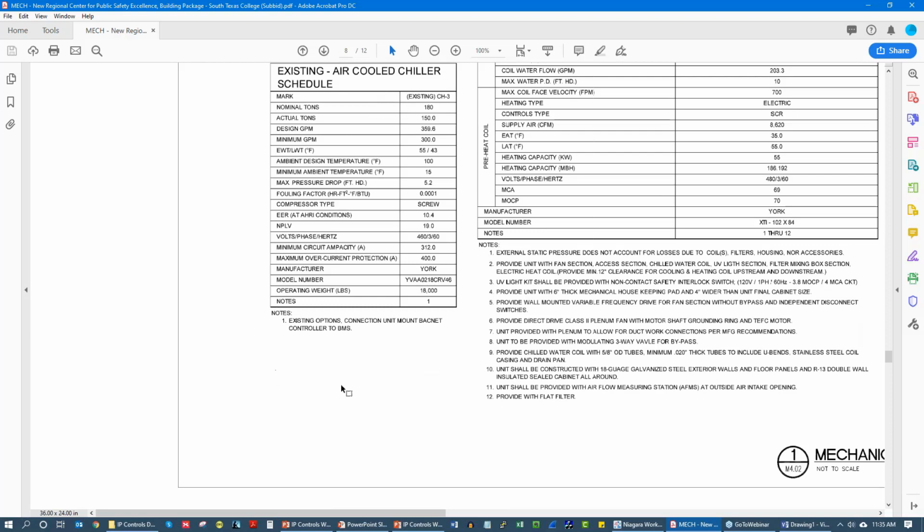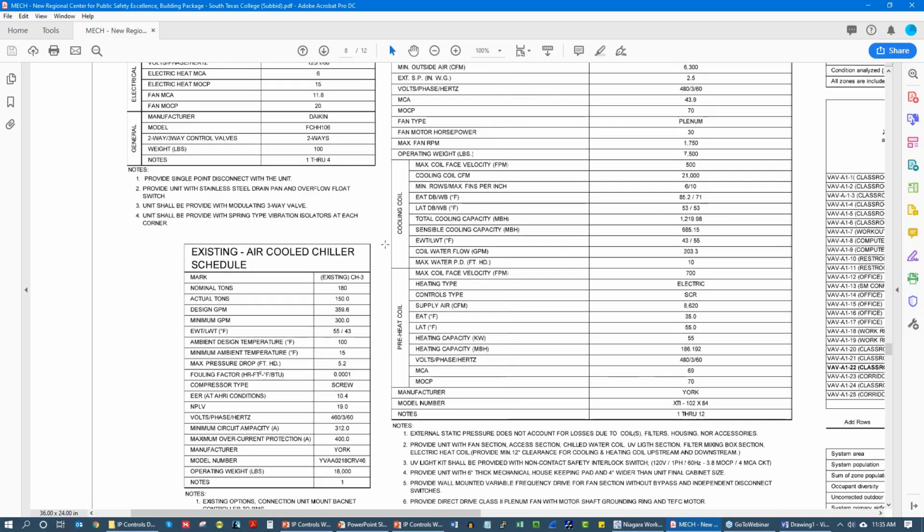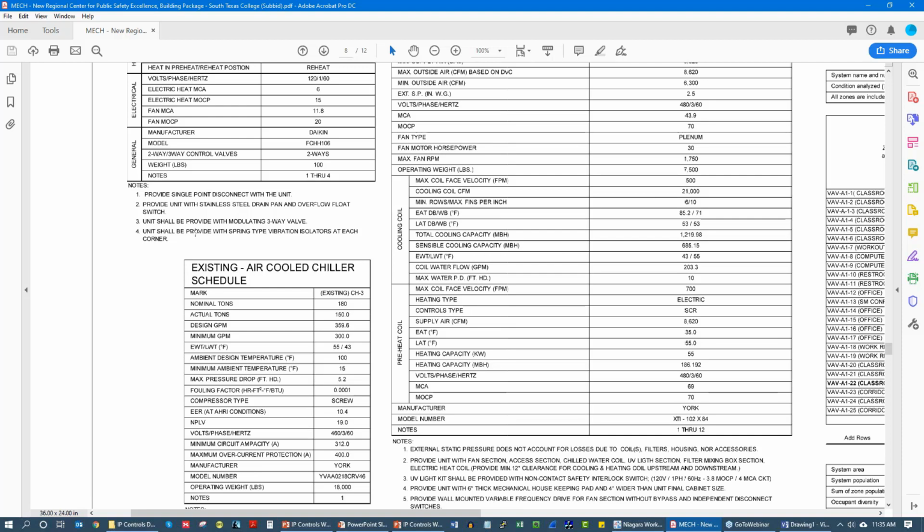So we know we have 28 devices. We know we are going to need, at a minimum, one port for the bus and 3 ports for the star, and probably a port for our supervisory device. So we're looking at 4 plus 1 more, so that's 5 ports that we're going to need from IT. And we know that we have 28 devices.